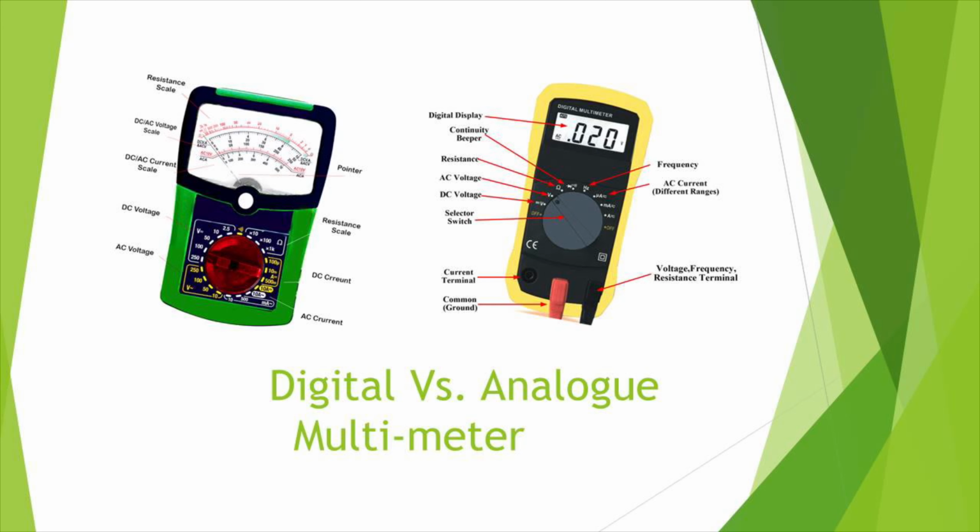Digital multimeters, often abbreviated DMM, have an LED display, commonly 3 or 4 digits wide. However, there are some bench models with 5 or 6 digit resolutions. Some have a multi-function selector switch or push buttons to select the ranges, but auto-ranging types are also available. Some DMMs have hold and max or min buttons that can capture the maximum and minimum value of a changing signal. There is no mistaking the reading from a DMM, and they do not rely on calibration.